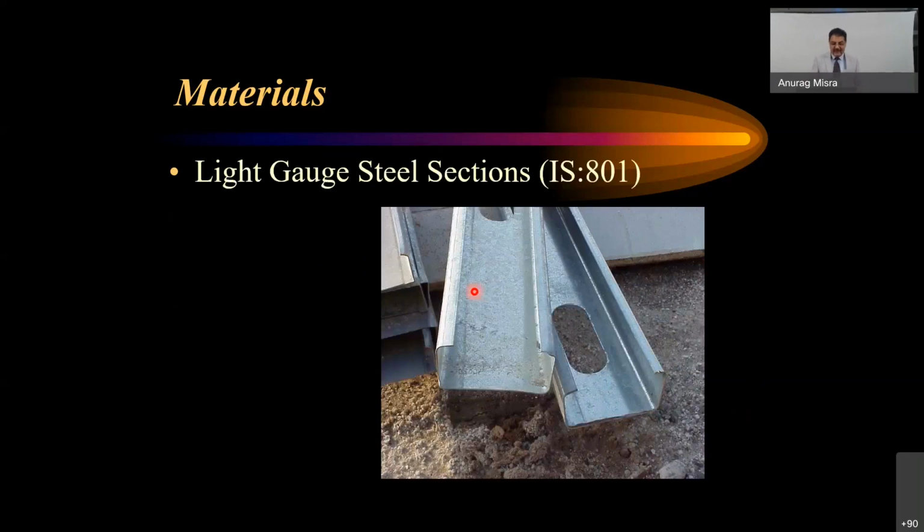So some of the steel, I am not going into the structural steel. We procure them in the form of plates, and then built-up sections are created for pre-engineered structures using HR plates, where you could get steel plates from 6 to maybe 50 thickness. Most of the range is this. The majority of it is used from 8 to 25.